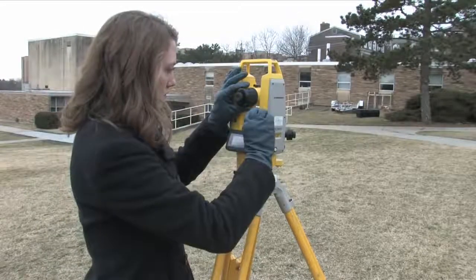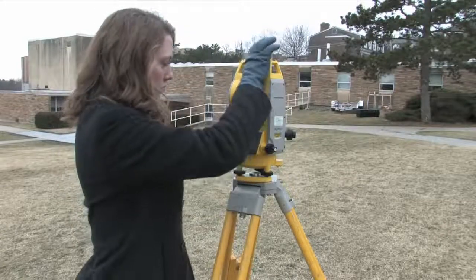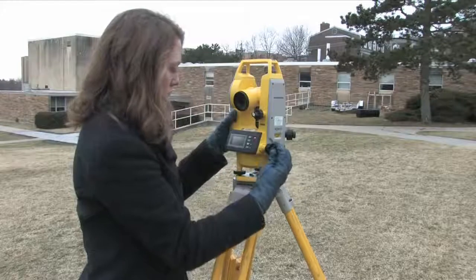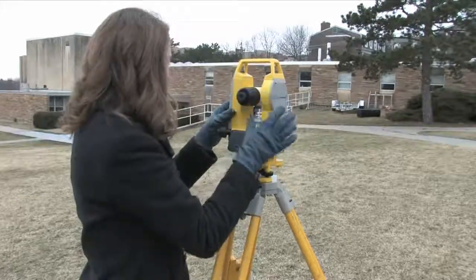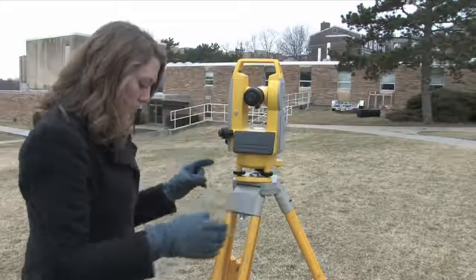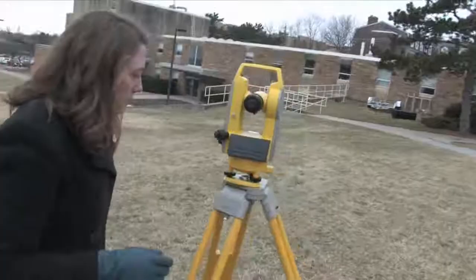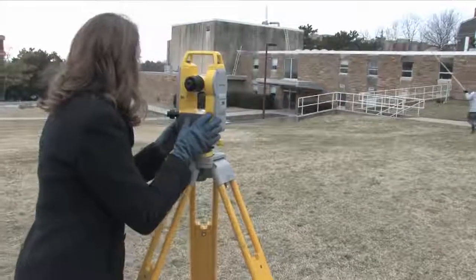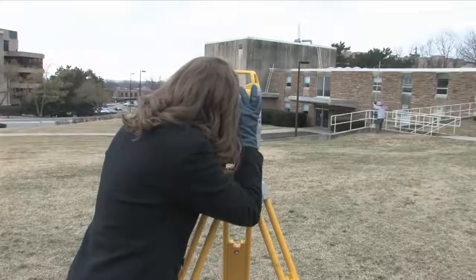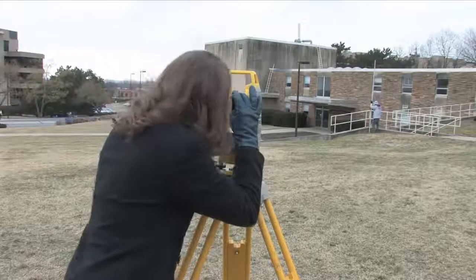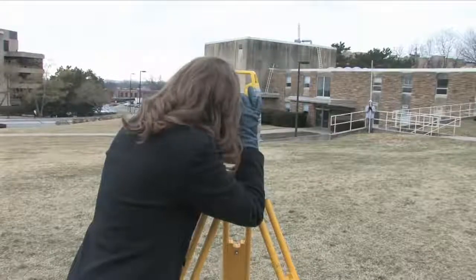Next, we will proceed to unlock the vertical angle lock and then rotate the scope 180 degrees so as to plunge the scope, and then we will unlock the horizontal angle lock and rotate the instrument so that the front of the scope is now pointed towards point A. Once the rod person has returned to point A, the instrument person may proceed to fine-tune the instrument back on the HI. Notice that the instrument controls are now facing away from you.